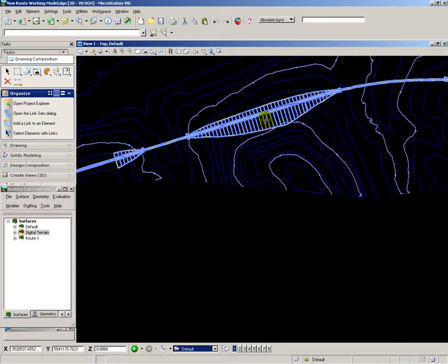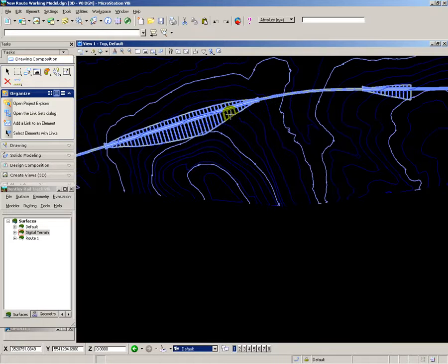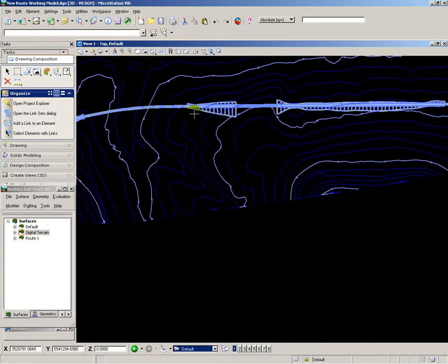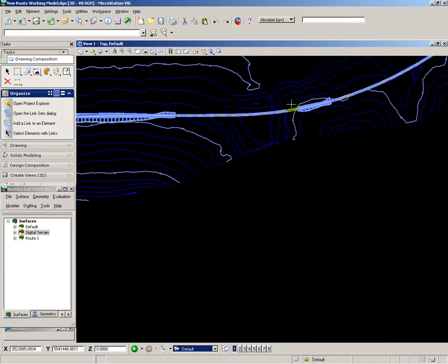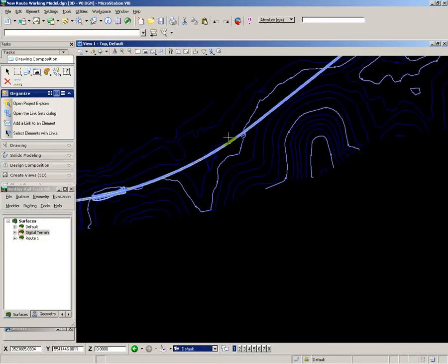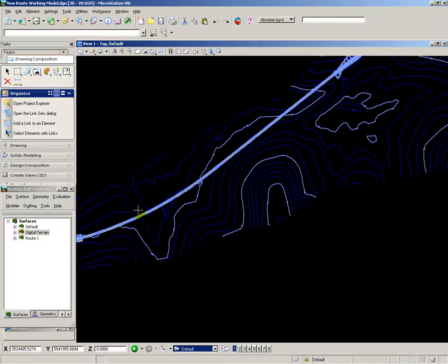And again, moving out of the hillside a little bit here, again could probably avoid most of this excess cutting in the sidelong ground. This tunnel here could be easily avoided by moving the alignment again very slightly out and perhaps extending that viaduct to around here. Long viaduct through here, it may be more convenient to realign that so that it touches the ground around this area to facilitate construction.